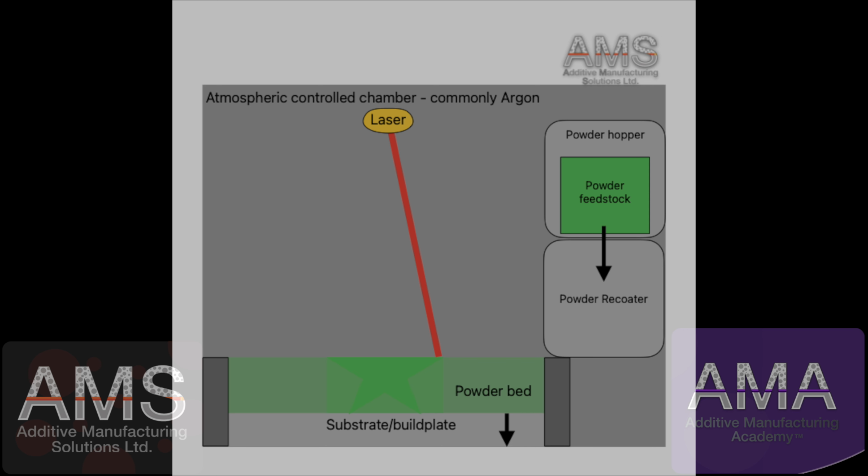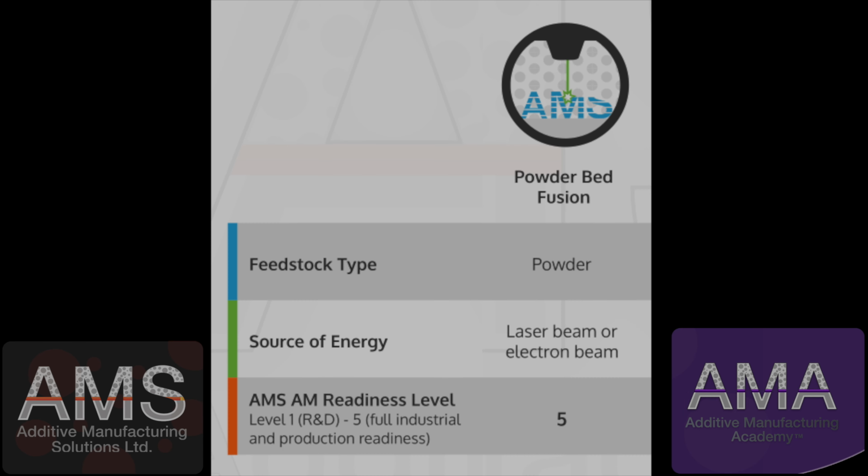The additive manufacturing process of powder bed fusion with metals is often called selective laser melting. Selective laser melting is a really good definition because we selectively melt using a laser beam. So when we are creating our parts, we select where the laser melts as per all of the other additive technologies, but also what's really important here is we do have a full melt process.